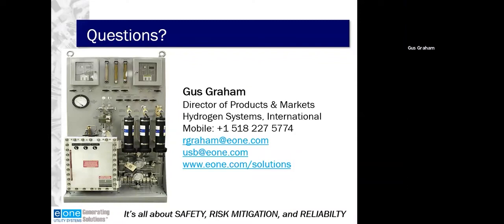The gentleman earlier who was asking about hydrogen consumption, sometimes plants that are running at a 95% point when they go into increased scavenging mode are finding that they're consuming just too much hydrogen gas. So if they adjust that point in the control room to 94 or 93%, obviously with the consultation with their GETA, they'll find that they reduce their hydrogen consumption while maintaining still safe purity levels on the ends based on the age and condition of the seals on that generator.